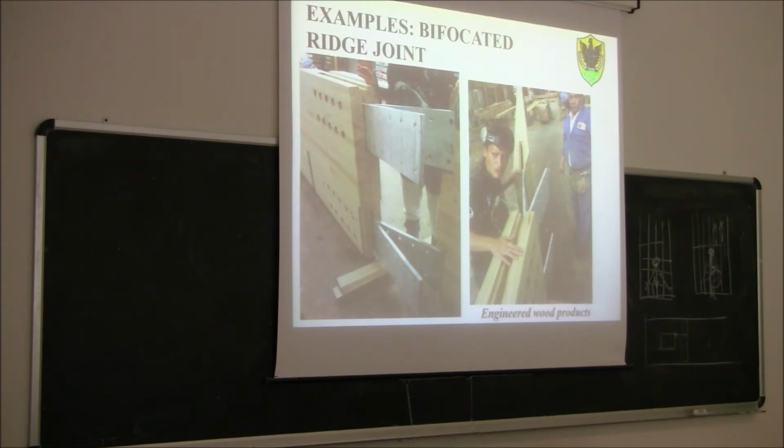You need to connect basically the fibers which carry the compression with the fibers which carry the tension. So the idea was, you see, basically to cut a hole inside here and to slot inside a steel plate with some holes. So this is the steel plate, these are the other two plates going into one beam and the other, and then the connection here is done using some bolts. So in this way you can transfer the compression force in one direction or the other, and then you can transfer also the tensile force to the bottom side.